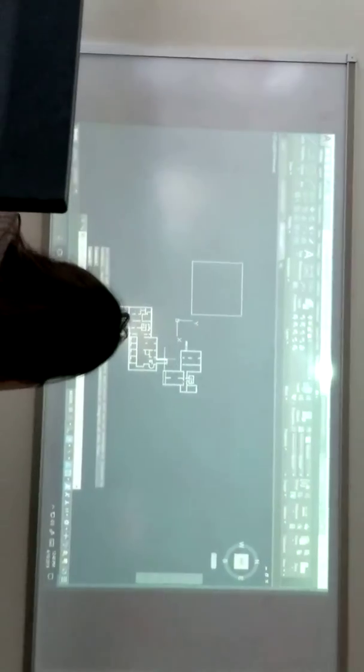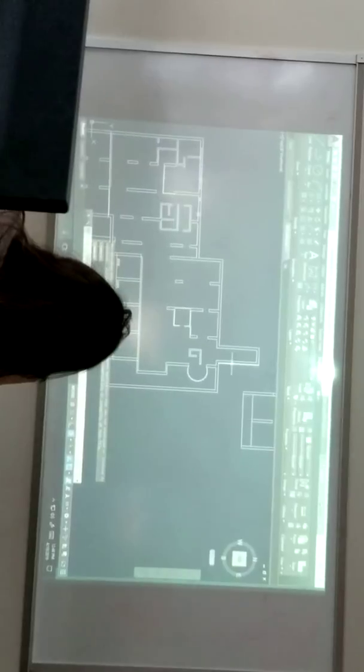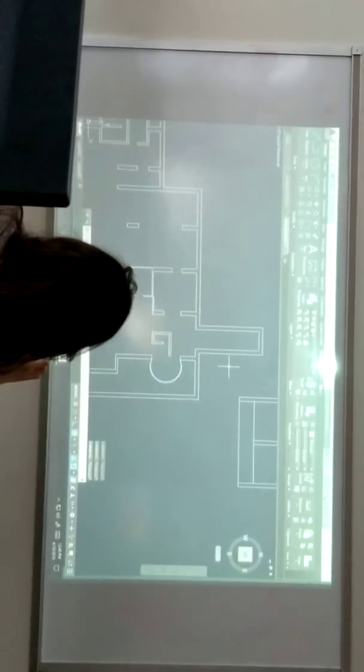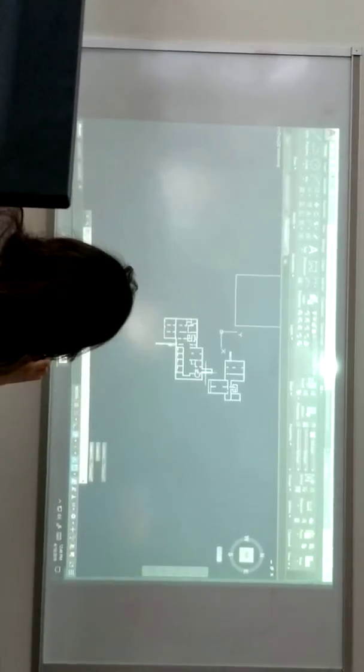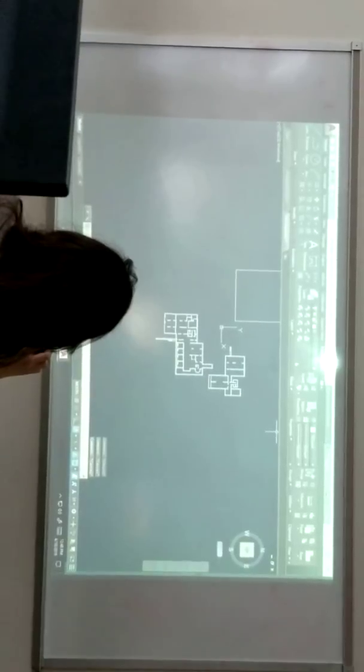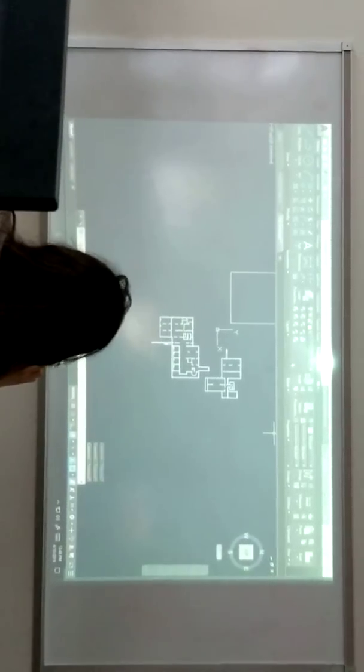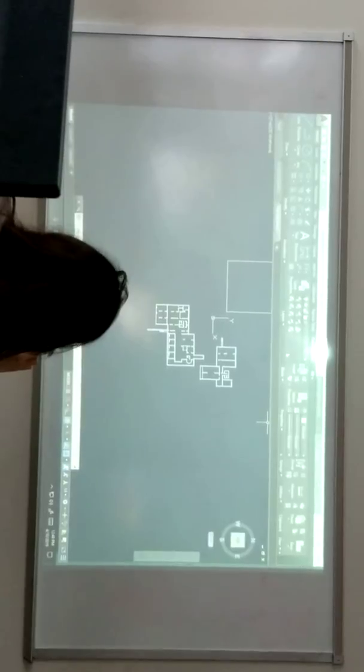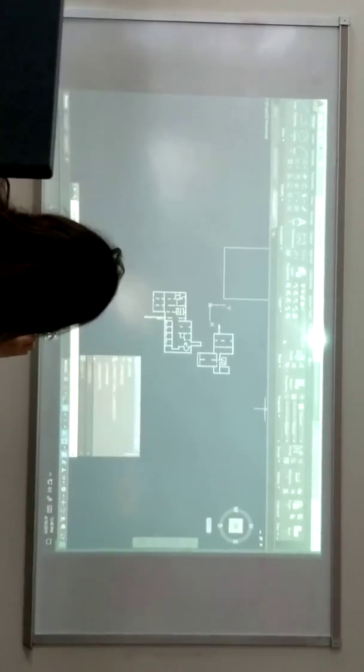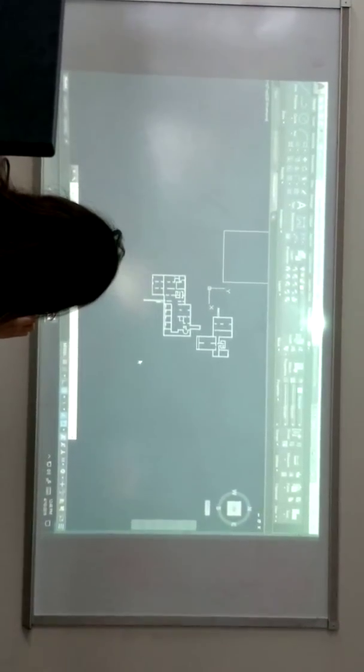You see me opening the DWG file. So this is my line weight. It looks pretty good, right? Now I can use these lines and just change them, but what I generally do is use those as a guide. I'll create a new layer. If I want to create new layers, what should I type in? Layer. Technically layer properties, but if I just type in layer, it'll come up.